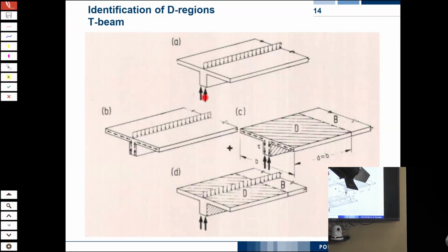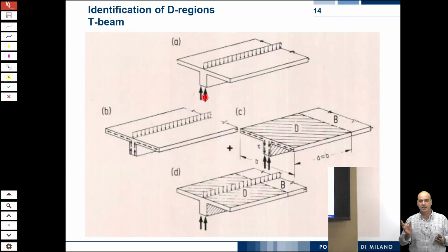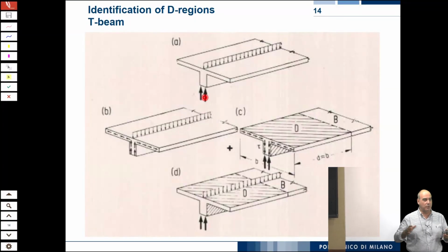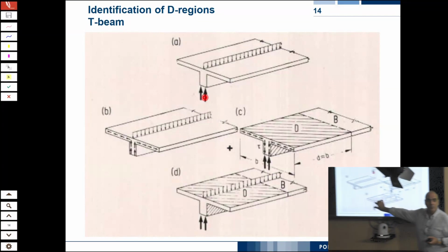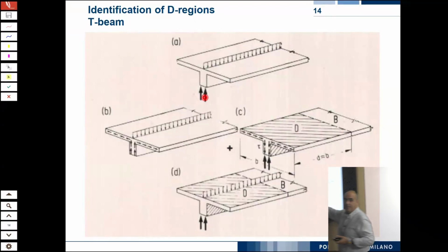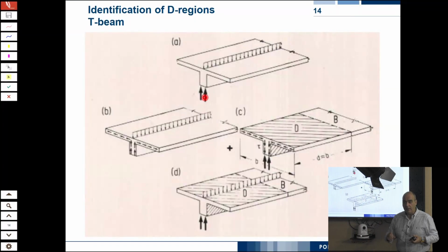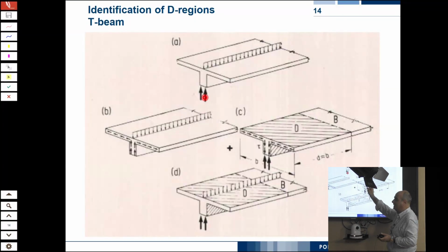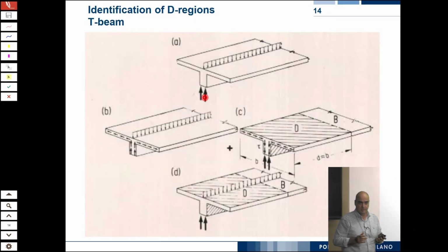I don't remember who came yesterday with an example of a composite beam column. Okay, yeah, that is something like that. You have this part which is your beam. Actually, your beam was an inverted T because you also had the plane. And then you put the slab on the top. If you make the slab collaborate with the beam, which means that you must have the reinforcement coming outside and you complete with some casting, then from a certain point onward, you can make them collaborate. So you can have a T or an I cross section.